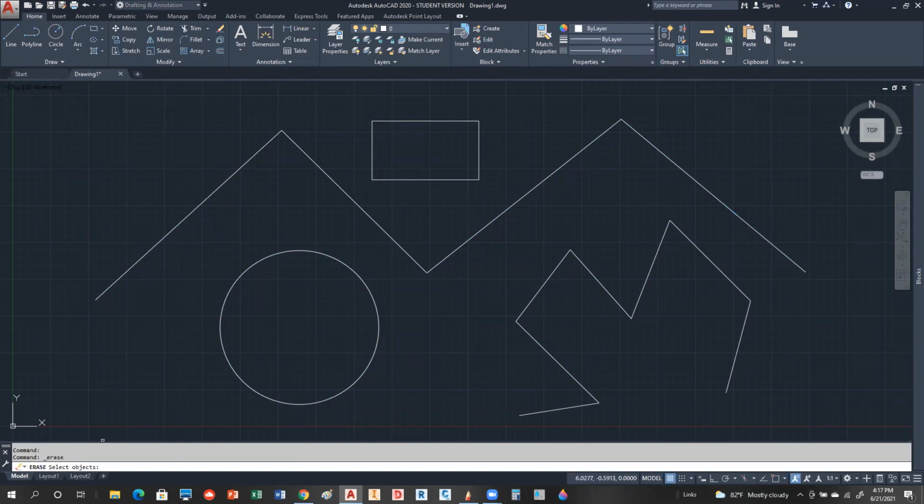And so notice what it says. It says select. Well, I'll tell you, yeah, that's fine. So we've got select objects. So notice erase is a little different in the way it looks, but if you take your pick box, it selects. If you do an implied window, it selects. Okay, so we can see how that works. That works exactly the same way. Let's go ahead and hit the escape key.